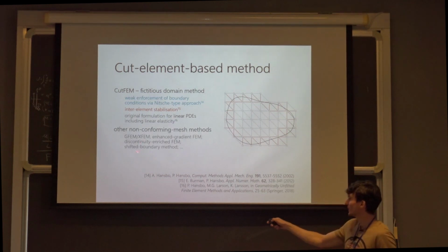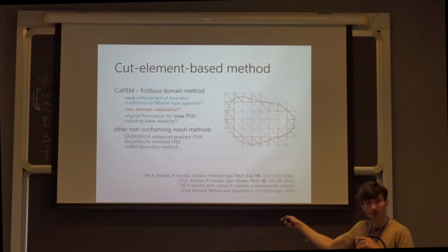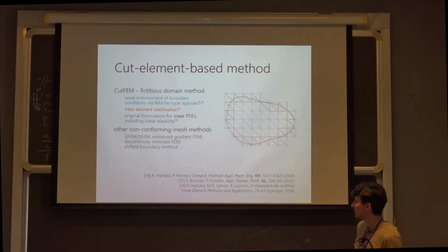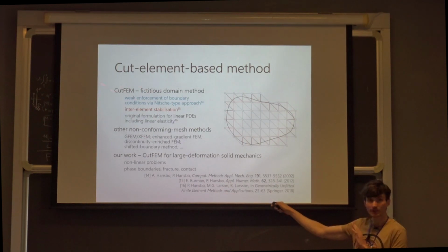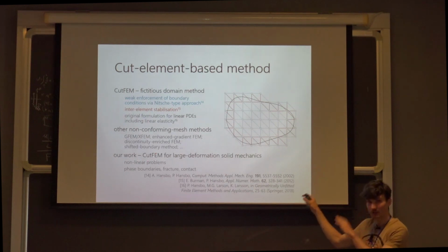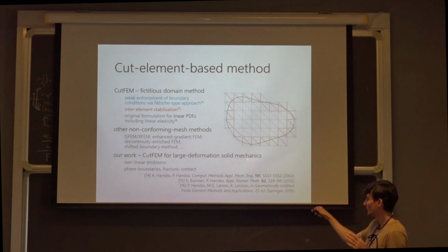I probably should have mentioned first that there are other non-conforming mesh methods. A lot of people worked on GFEM, XFEM, there is enhanced gradient FEM. There is also a really cool new method, the shifted boundary method. I really like it, but didn't have much time to look into that. So there are other methods, but we work on CutFEM. CutFEM has been done for linear problems, and we specifically work on CutFEM for large deformations in solid mechanics.